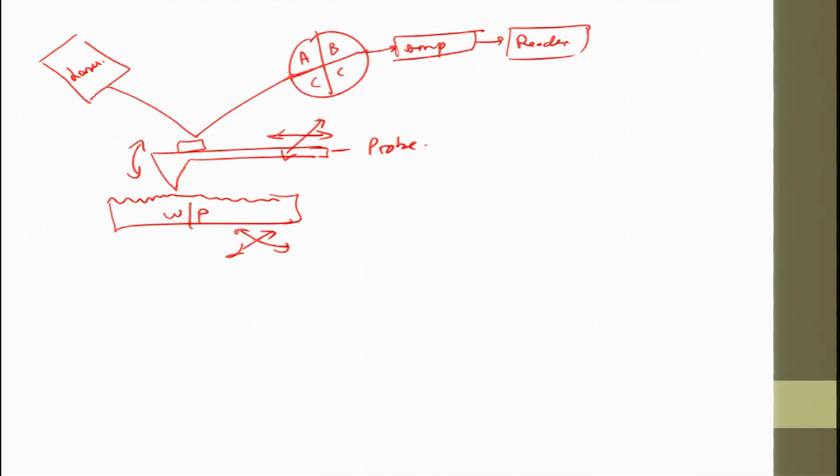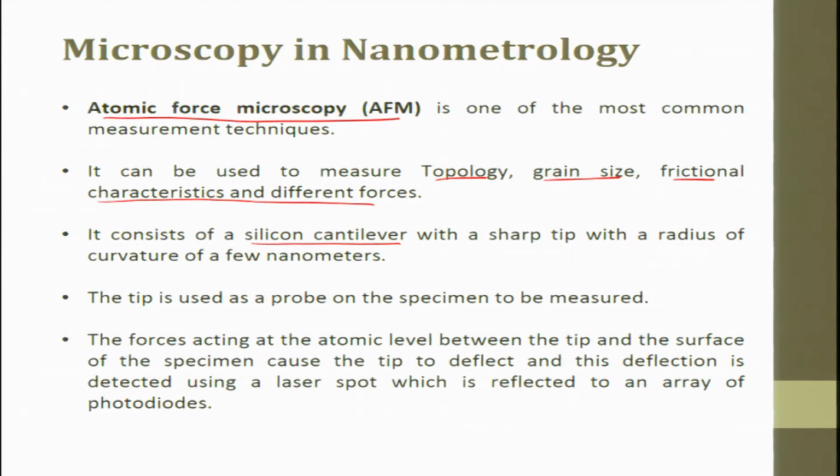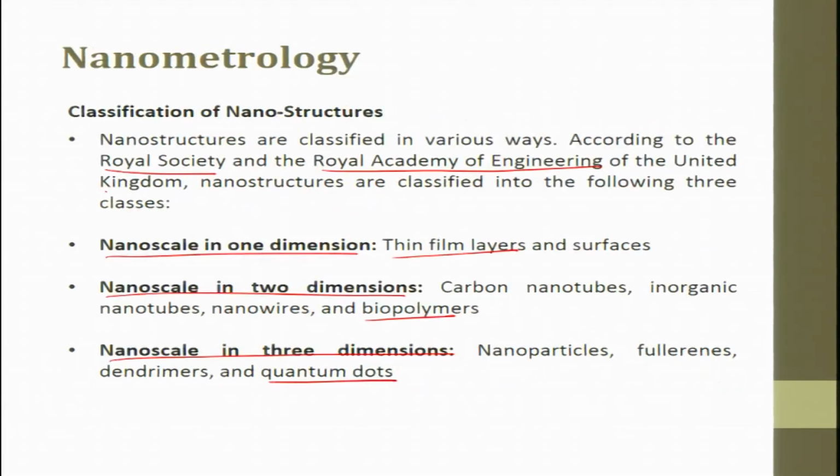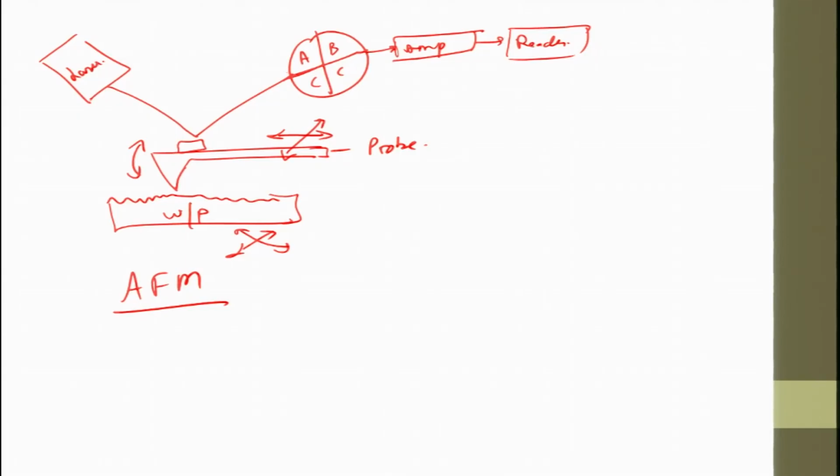Then we read the variations in the height. It is just like your surface measuring device, but here we measure at nanometer scales. So, this is the atomic force microscope. This topic is very interesting in its own right. Roughness measuring is also used here, but the stages will be moving on a piezo crystal, or the probe will be attached to a piezo crystal. Either one will be there, and here we use a damper so that no vibration is felt.